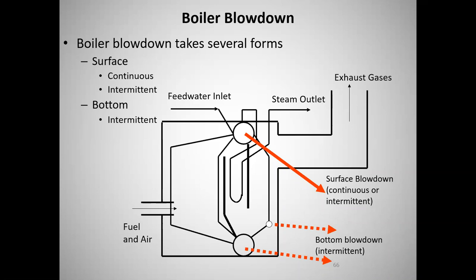Well, a lot of people don't have that. So what they do is old Joe, the boiler operator, will go in there and there's a big valve on that, and once a shift he'll go in there and throw that valve open and drain boiler water down the sewer, count to 10. Throw it open, count to 10, count to 5, count to 15, whatever the recipe is for the plant, shut that thing off, goes back, sits down in the control room again. They may do that once a day, they may do it once a shift. Depends on whoever is managing the boiler.